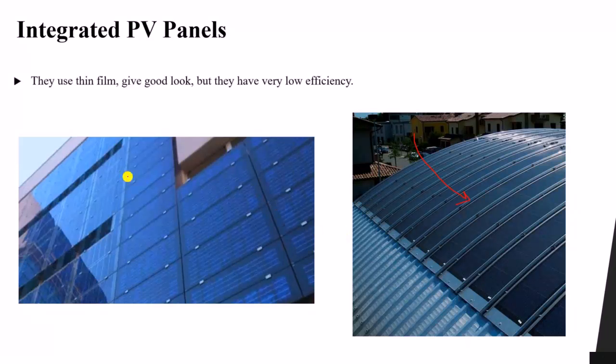We said before that we use the thin film when space is not important for us. They give a good look and at the same time they have very low efficiency. If you remember in the previous lessons, we said that the efficiency of the thin film is about 7%. So it has very low efficiency. That's why we install a large amount of these panels, and at the same time it is very cheap.